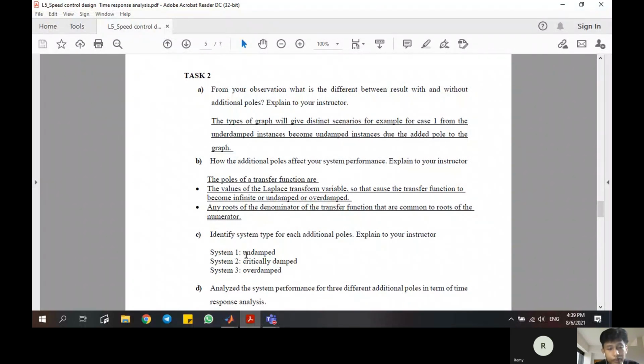Whereas for system 2, it is a critically damped case. Loops that respond quickly are called critically damped loops. An example of this type of response would be a steam heating coil for a jacket type product heater. The jacket allows steam to circulate around a kettle and heat the product without touching it. Anytime the steam valve is opened or closed slightly, the temperature will change quickly.